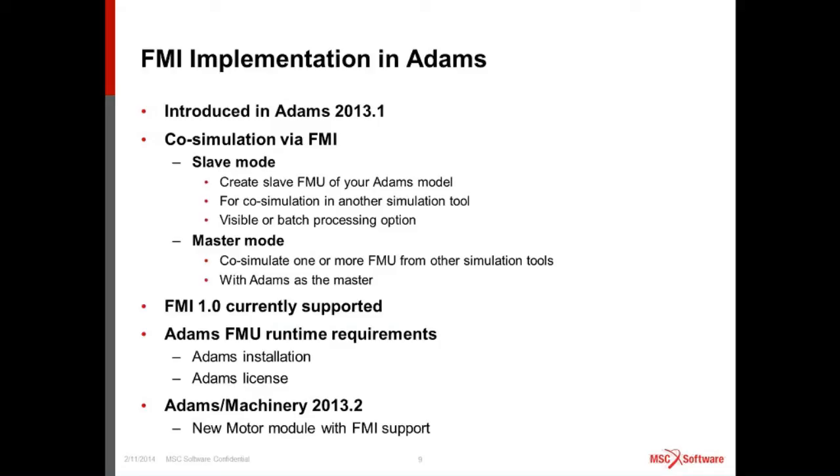For slave mode, you can export your Adams model as an FMU. As I mentioned earlier, the ADM, CMD, or ACF file, and all the model relevant files will be included in that FMU. And during the co-simulation, the other tool will call Adams, and you can specify whether the slave FMU will be visible or not.